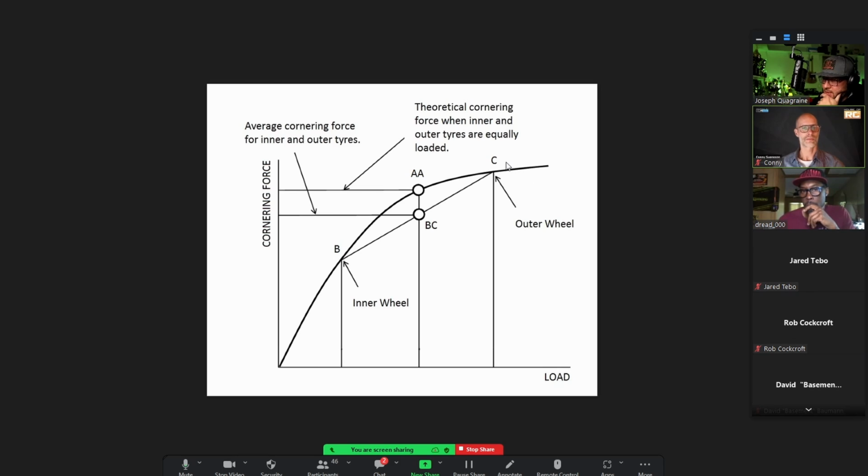So this is important to remember, because when we are adjusting our car, we can think about the distribution of load on left versus right tire in a corner. So how much load are we transferring? If we transfer more load, we have less grip available in the corner. If left and right tires are more equally loaded, we will have more grip available in that corner. This will become more clear as we go on, but I needed to show this to you first.